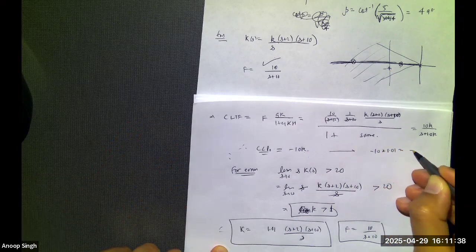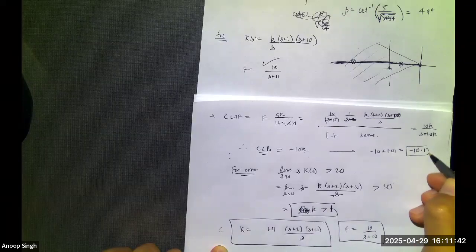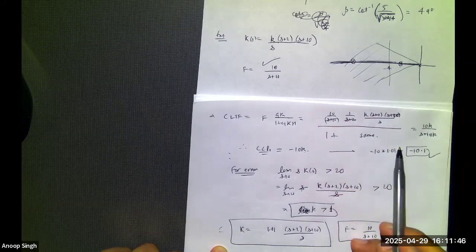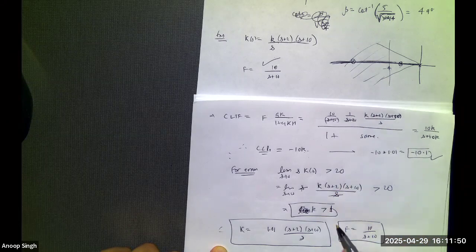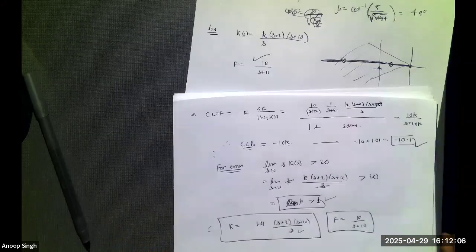So the closed loop pole is in the right region, and settling time and overshoot are done. It has a gain and an integrator, so my error calculations are done. And because the pre-filter times controller do not have more zeros than poles, my specification is done as well. Sounds good? So this is my controller.